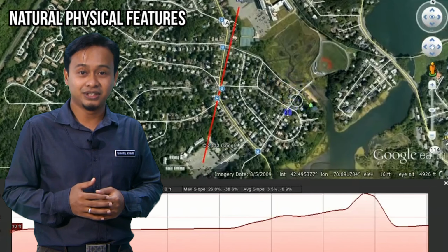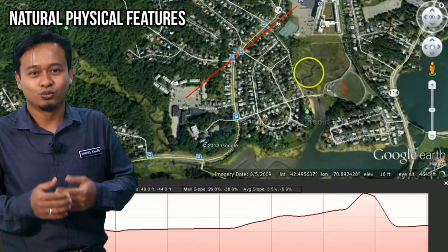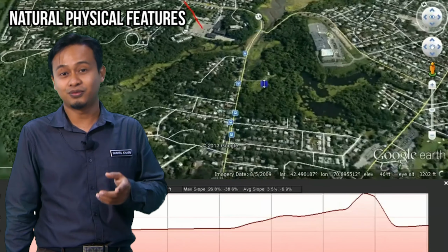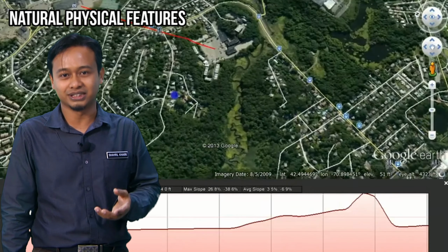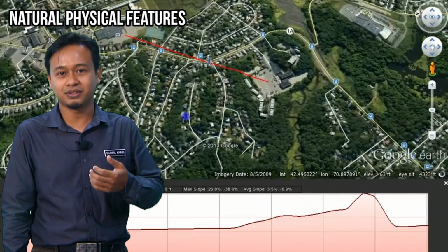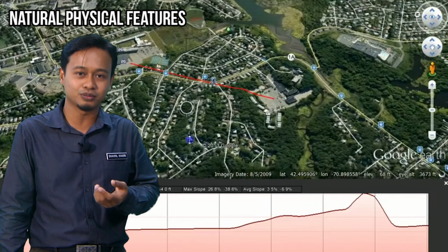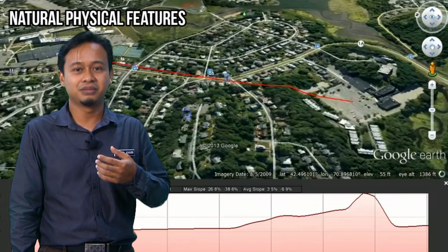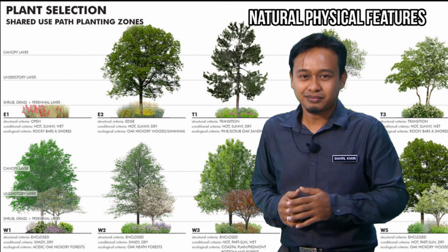Under the natural physical condition and features, we are required to attain any existing surveys and confirm the accuracy of contours, levels above sea level, gradients and also slopes, and the existing terrain. Note that some of these may be natural or artificial.